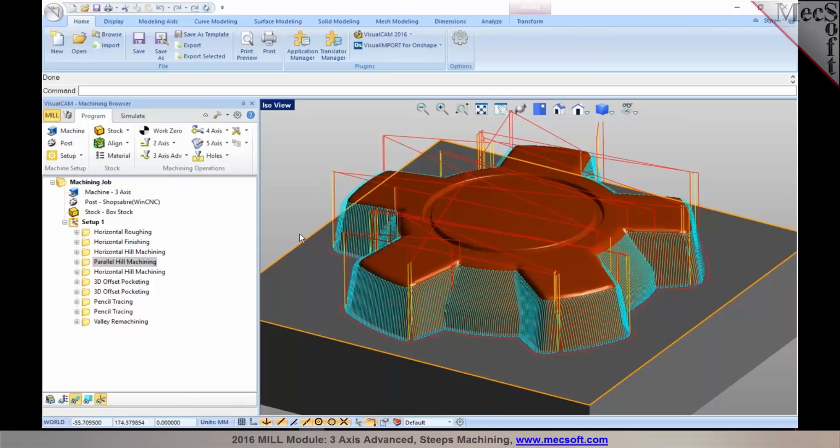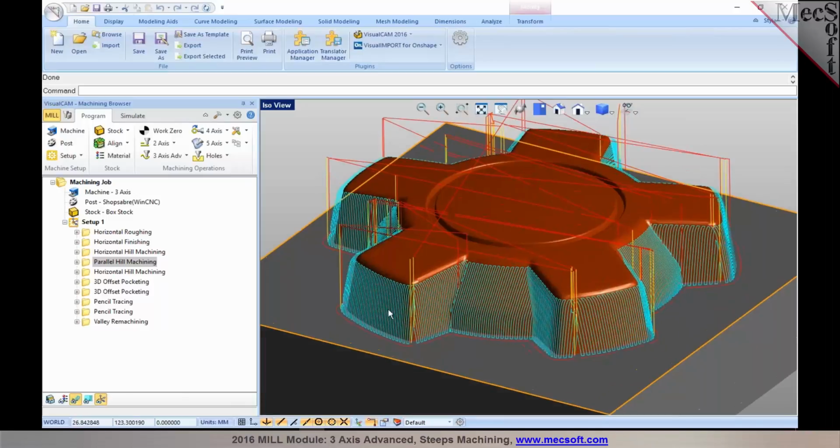Then, as many of you know, if you have steep areas at an angle that is not perpendicular to your angle of cut, you're going to leave a lot of material because of the nature of the toolpath. If the steep area is parallel to your angle of cut, you're going to leave a lot of scallops on the sides of these walls. So that's why if you do a cross cut, you can come in and clean out just those areas.